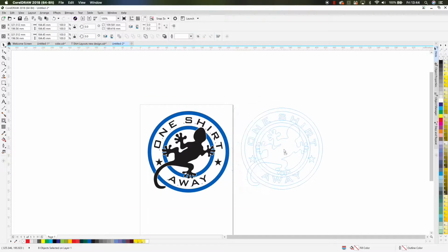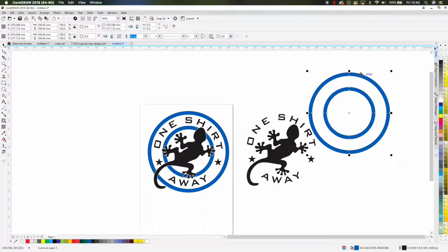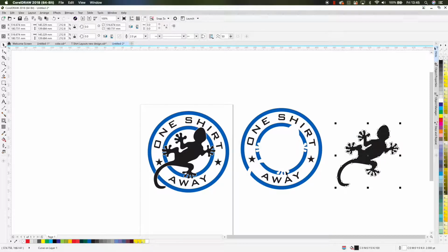I'm going to show you another way. So let's take this across. I'm going to highlight all of it, drag it and drop it down and click once with the right mouse button. Okay, so what I want to do with this now is I'm going to select this inner circle and outer circle, and I'm going to go Control L, and I'm going to combine them. So if I move it away now, you can see that it is actually one component, even though it's two sets of outlines. So go Control Z, and I'm going to grab my gecko once, and I'm going to press the Shift key, and then I'm going to select the outer circles, and I'm going to go up and trim. And now when I click on the gecko and pull him away, you can see he's cut that out.